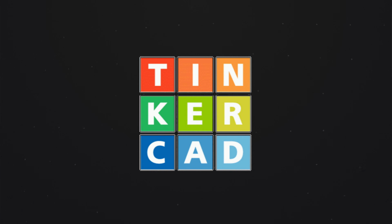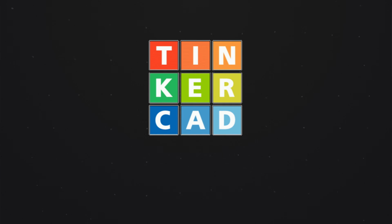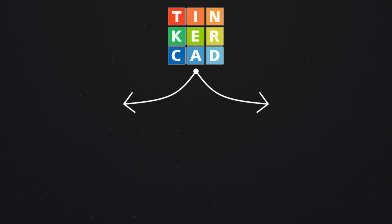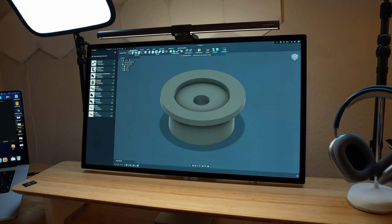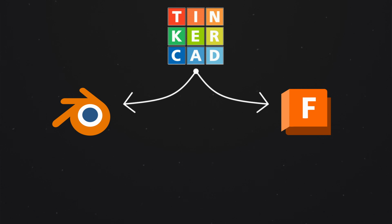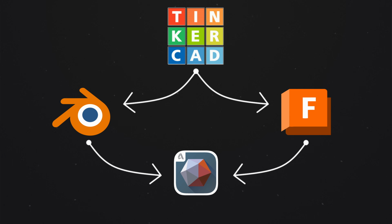Now I've shown you so many programs that it might feel a little bit overwhelming. So let me simplify it. Start with Tinkercad, but after a week it will probably feel too basic. Then ask yourself one question: do you want to design functional parts or sculptures? Functional parts, learn Fusion 360. Sculptures, learn Blender. If you prefer working on an iPad, Shaper 3D for functional parts, Nomad Sculpt for sculptures. Once you're comfortable, also take a look at Meshmixer for editing STL files.